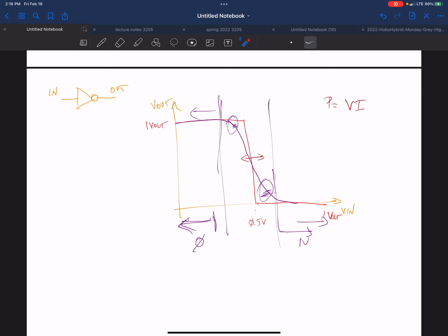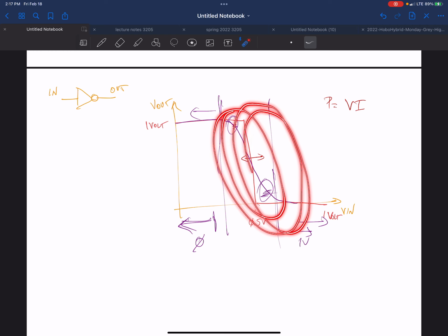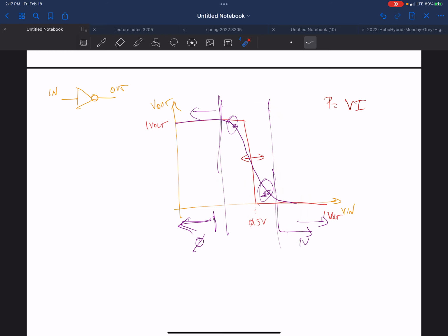They don't really act like that at 45 nanometers. There are always second order effects where your saturation isn't square law dependent, all sorts of unfortunate stuff happens. The more aggressive the process, the gnarlier this looks, but you accept that to pack more stuff in. Does that sort of answer your question? Yeah.